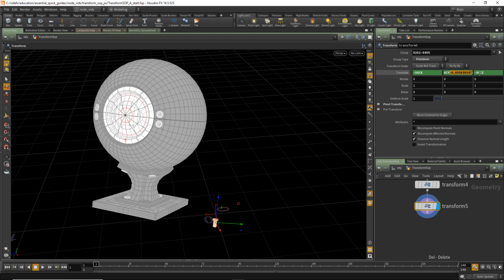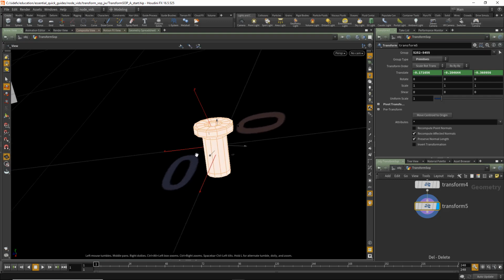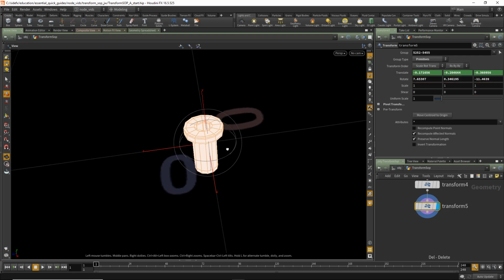Yes, it does. Now what the GCX, GCY, and GCZ does is it actually returns the centroid of the incoming group, and it puts it at the origin. Space G that on the viewport, and a few more rotate, just quickly rotate it into position and get it rough, and then we can do some procedural modeling.